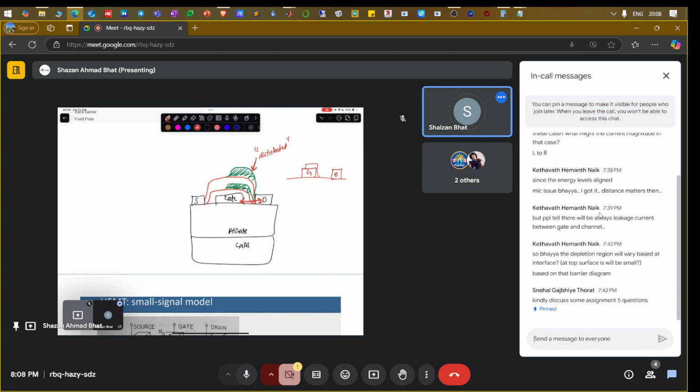Now if you go on increasing the field plates, the electric field lines might end up differently on different plates. You mostly apply positive at the drain and negative at the gate, so the electric field direction will look something like this. That is going to have an impact on the breakdown voltage that we covered in, I guess, week 3 of the session.